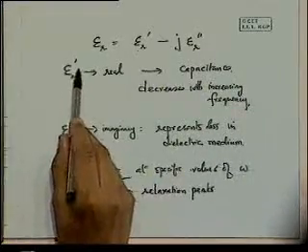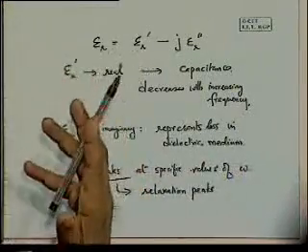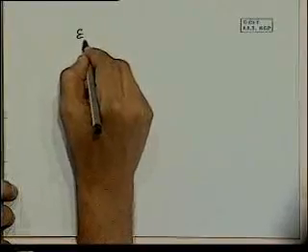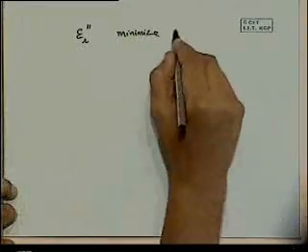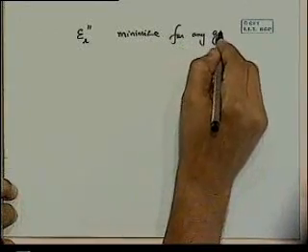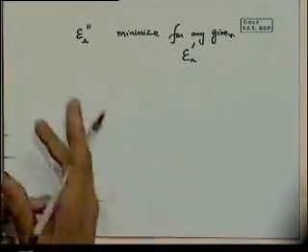So epsilon r dash gives you the real component, which is more or less what we've been writing as epsilon r in all our equations. When we come across it again, we are going to make use of the real part in our calculations. And epsilon r double dash represents the loss in this medium. What we really want to do is minimize it as low as possible for any given value of epsilon r dash. That's normally what we're trying to do: I'm trying to store charge, epsilon r double dash is the loss component, so I want to minimize it for any given epsilon r dash.